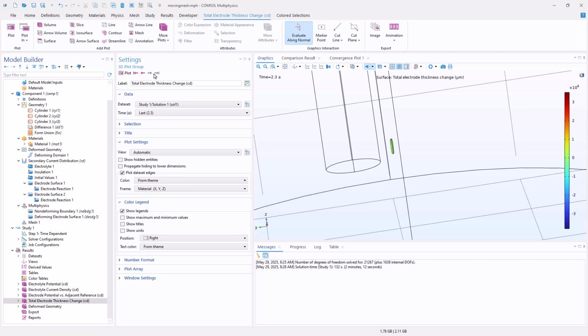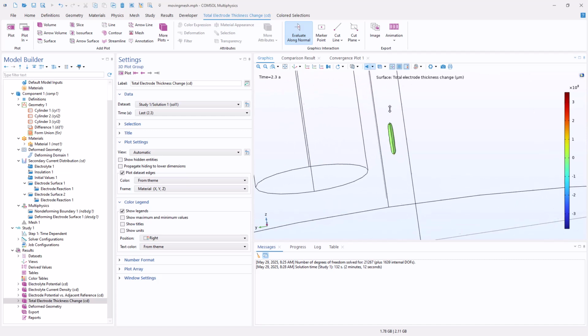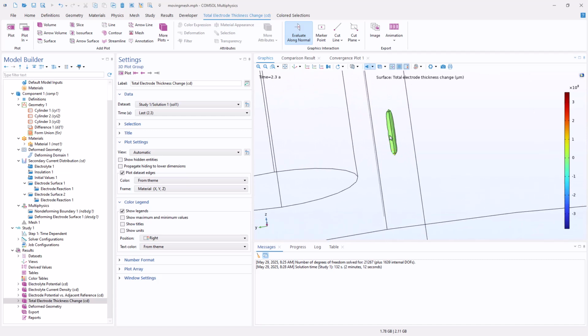And then you need to either do a remeshing, and in some cases that will only help you a while, because when it's completely consumed, you will have a change in topology, and that is not supported with this deformed geometry method.